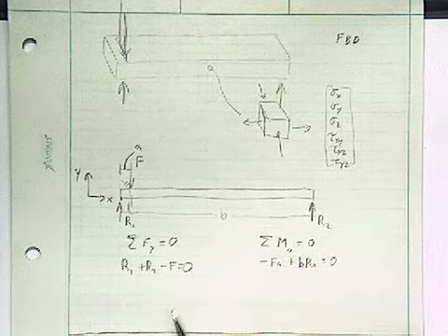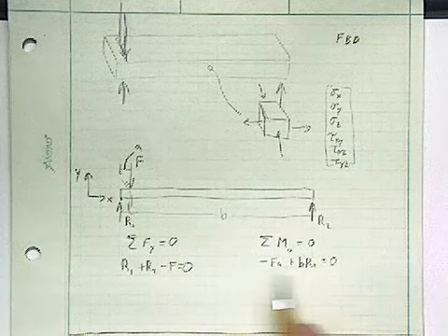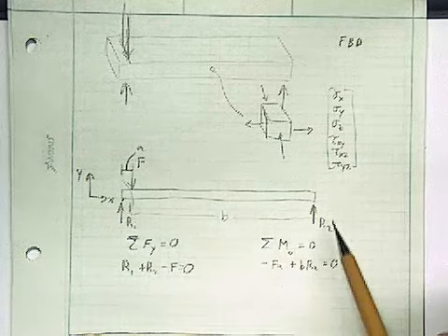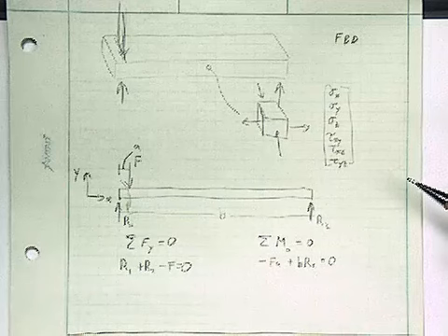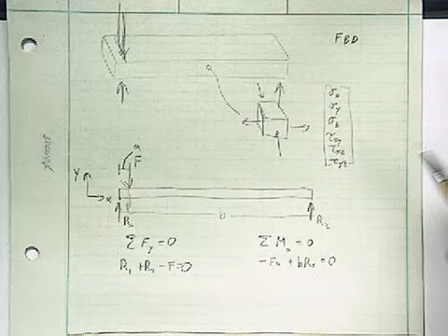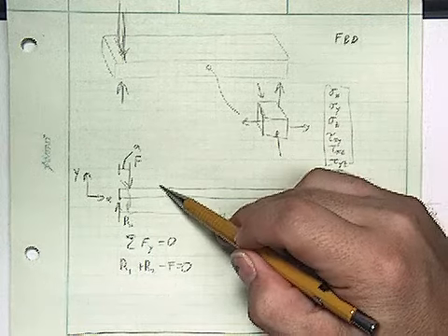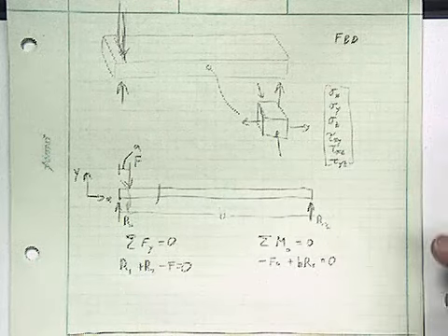So now with these two equations, if I know F and A and B, I can solve for R1 and R2. And that gives me the first step. This is just a simple free body diagram of a beam. Okay, so now from here, let's draw a different problem, and we'll begin to take a look at what happens if I were to slice the part at some distance and figure out what's going on at that location.